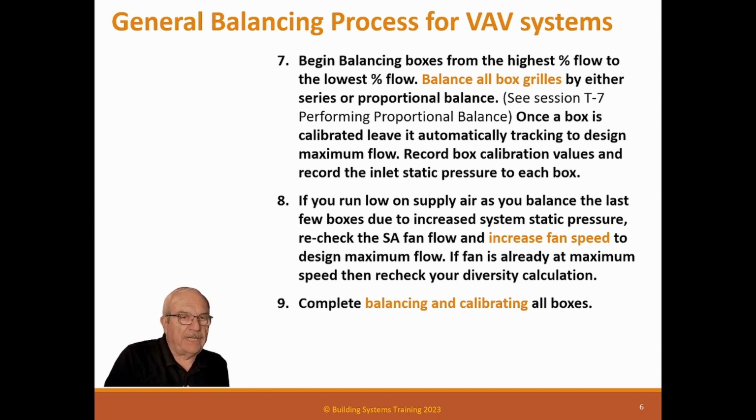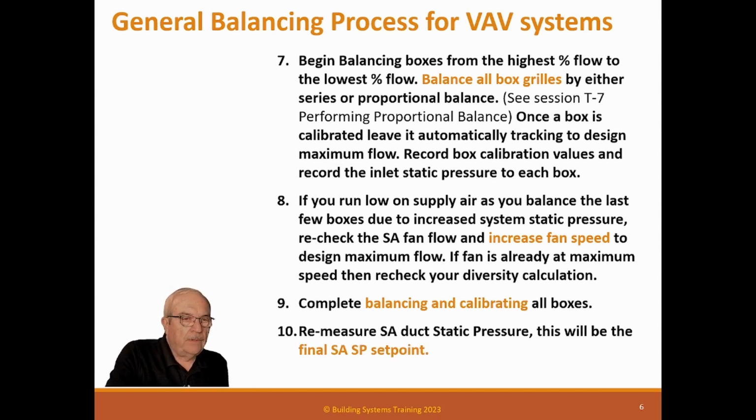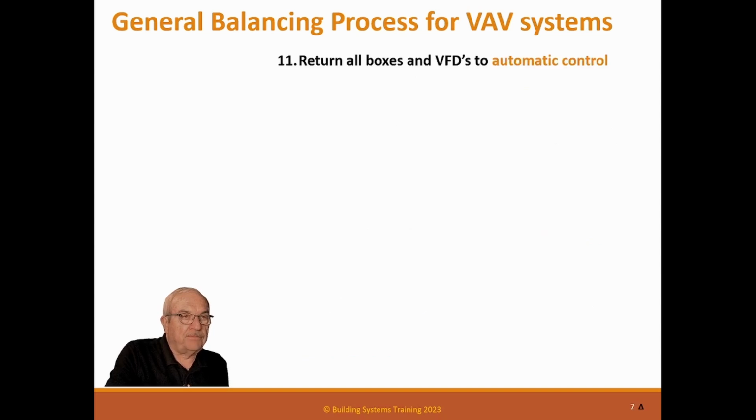Complete balancing and calibrating all boxes. Remeasure the supply air duct static pressure. At this point, this will be the final supply air static pressure set point. You balanced all the boxes. They're all locked at maximum flow. Your air handler is locked. Look at the supply air static pressure, and that'll be your pressure set point.